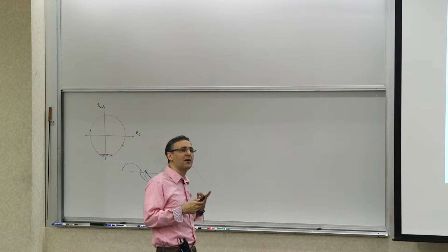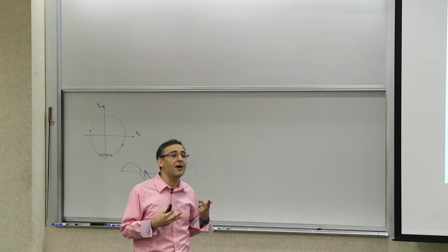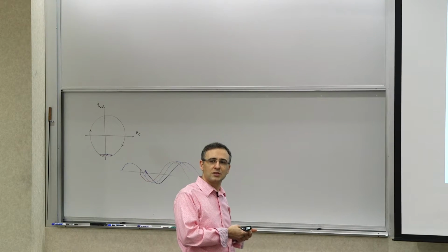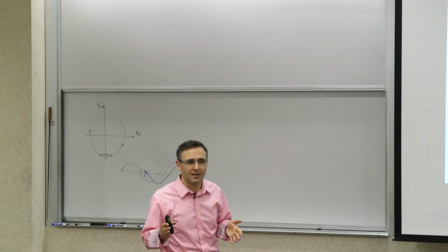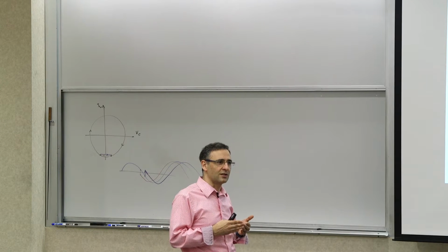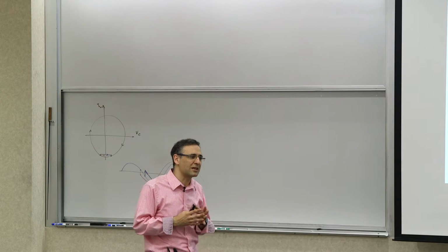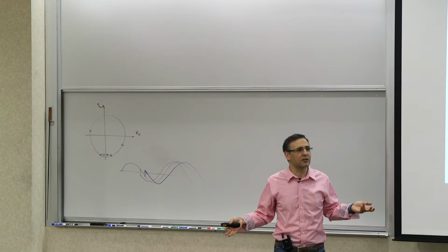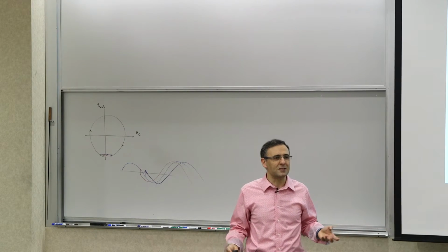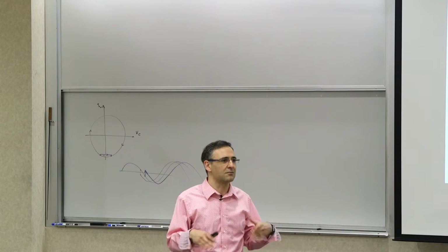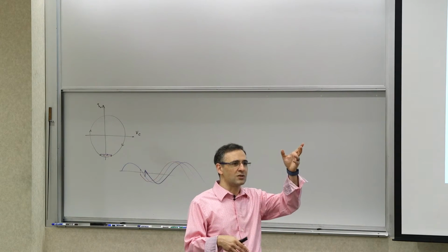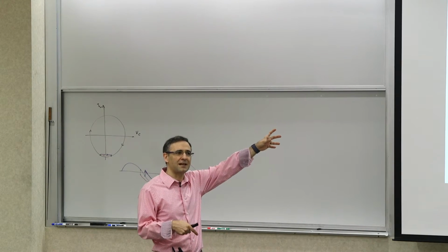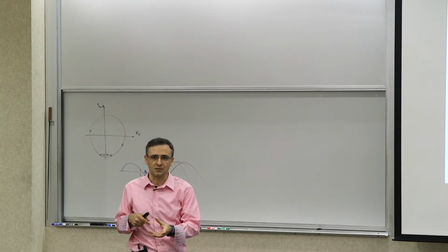Now, likewise, this also shows you how a low frequency perturbation can produce modulation in the oscillator, right? Why is this important? Because you remember we didn't have a good explanation of why the 1 over f noise, for example, the flicker noise, would show up in the spectrum of the oscillator. When we were looking at the Leeson model, we saw that it's noise in the vicinity of the frequency of oscillation that goes through that filter. But it didn't really explain how the noise from low frequency came to high frequencies, right?